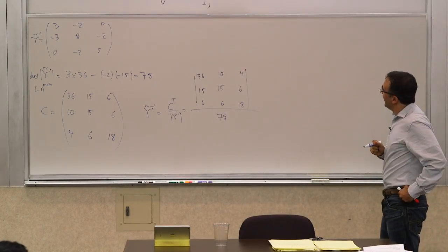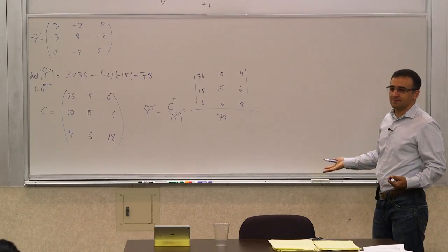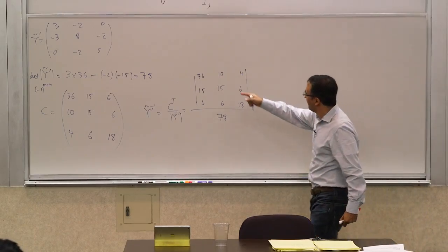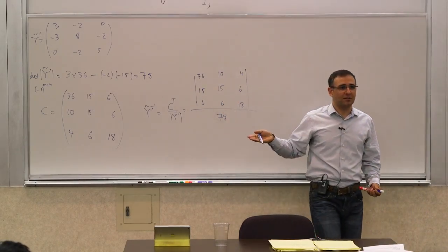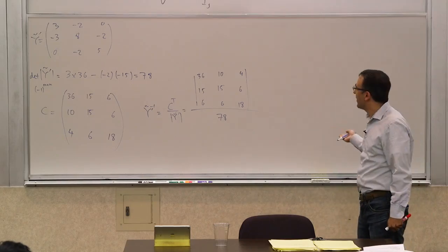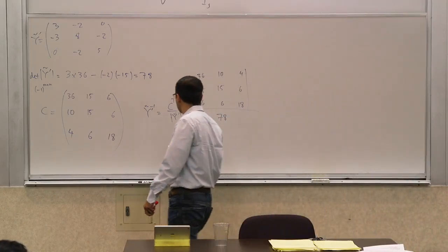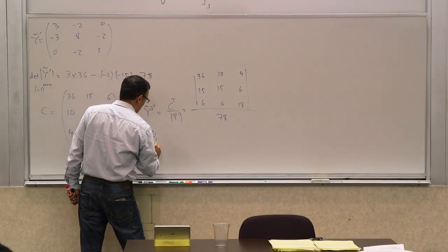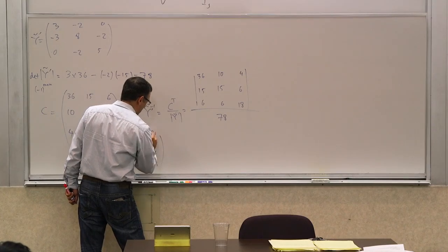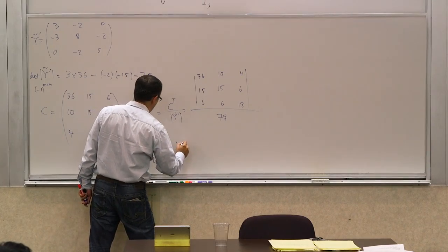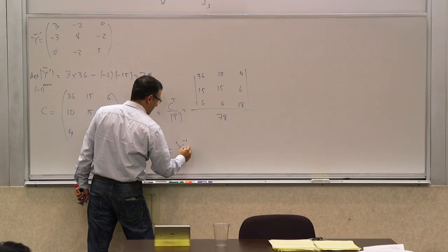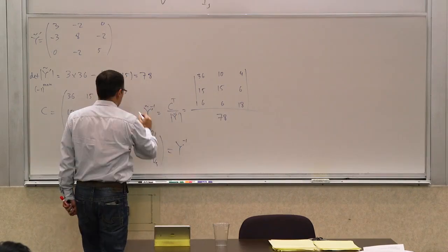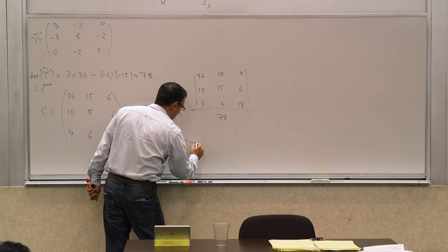All right. OK, so that's our inverse. I mean, you can try to divide this by that and see what they would be, but it's better to write it this way. Now, if I want to calculate my voltages, V1, V2, V3, what do I do? I just multiply this inverse by the I vector, the stimuli vector, right?